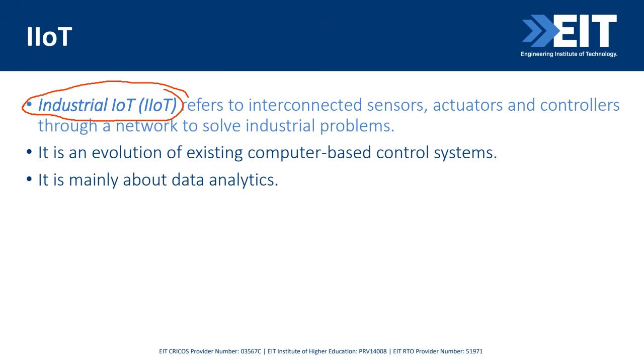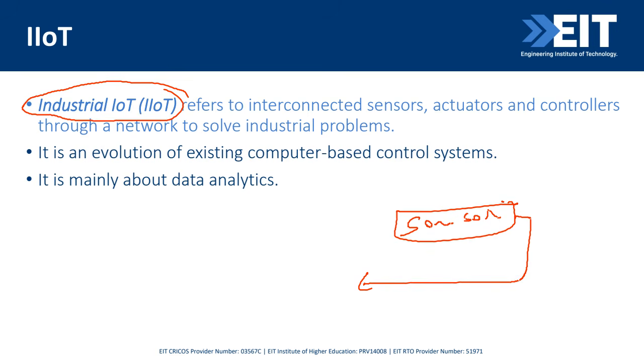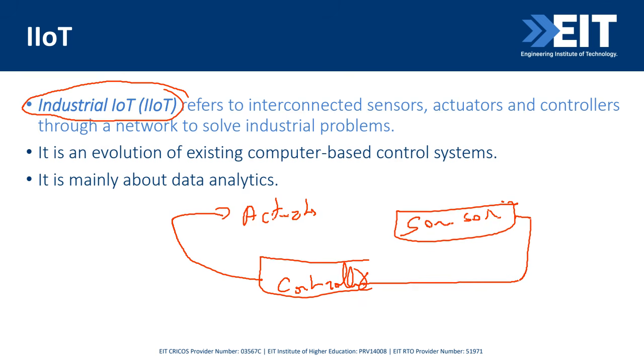Okay? Now, I'm mentioning a lot the concept of actuators, sensors, and controllers, in fact, because it is essential in industrial applications. It's essential when you do automation. So what do you need when you do automation? You have a sensor here. Your sensor will give data to a controller. The controller would decide by sending a signal to some actuator, and the actuator will affect your process, whatever the process is. P, I'm going to call it P. And then it's like a cycle. Typically, it's a feedback cycle.